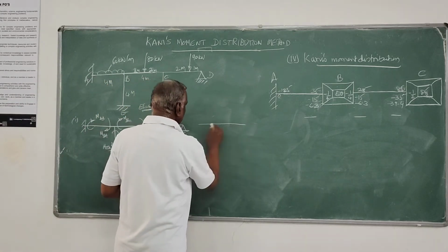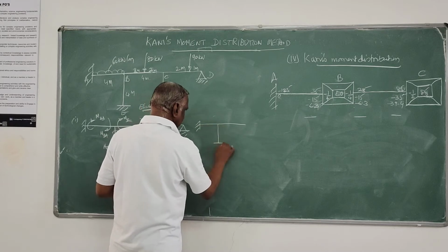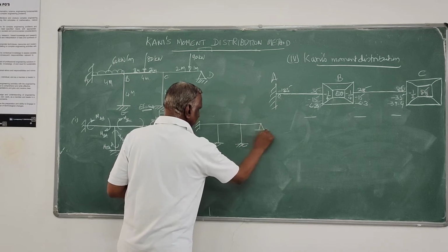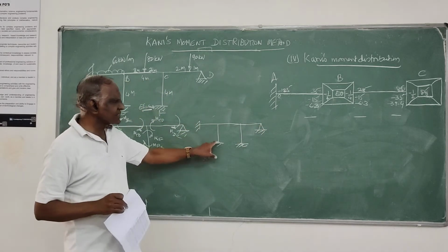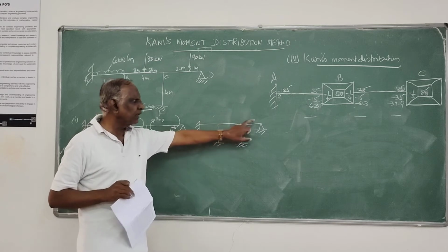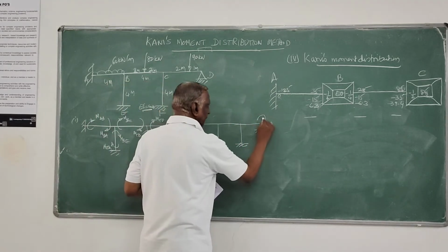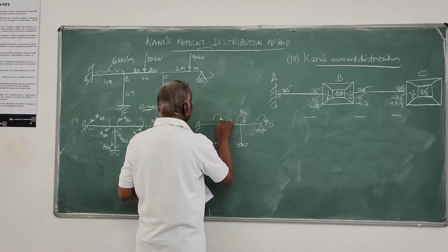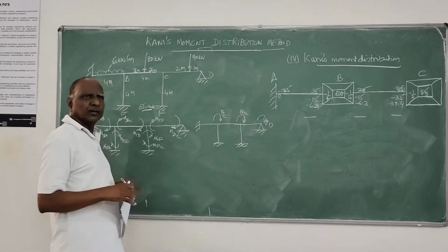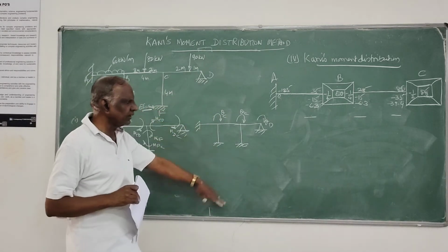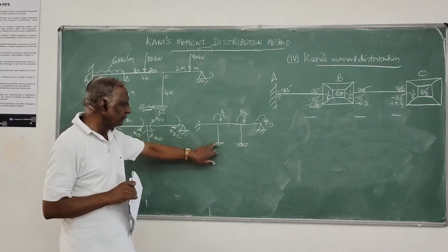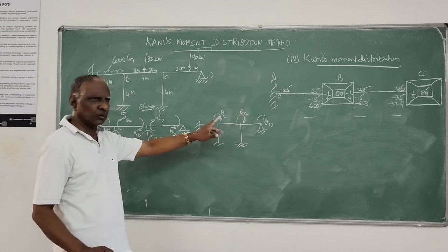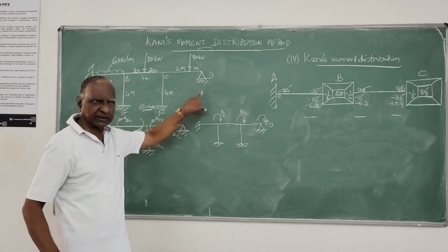Then we have to find out the displacements also at the ends of each member, possible displacement. So here fixed ends, no displacement possible. Here only rotation possible, that is theta D. Here also rotation possible. Here also rotation possible. Then translation, vertical translation is ruled out because vertical members are always fixed at the base. Horizontal member also. Here there is only one horizontal member in the total structure.